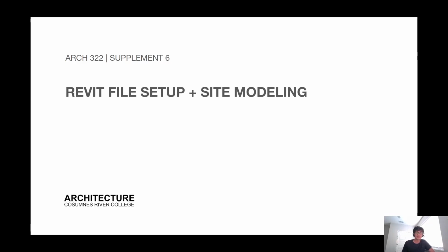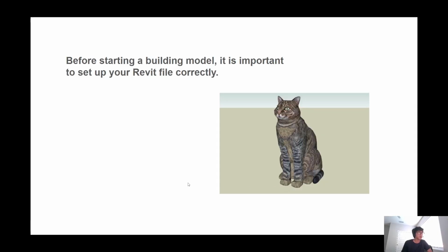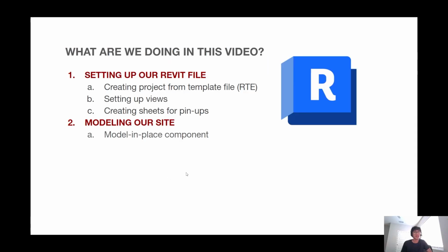Hey everyone, my name is Elijah, and this video is going to go over setting up your Revit file for your design project and also modeling the site around it. As a very general but important tip, before you start building a model, it is important to set up your Revit file correctly. And in this video, we'll be doing just that.